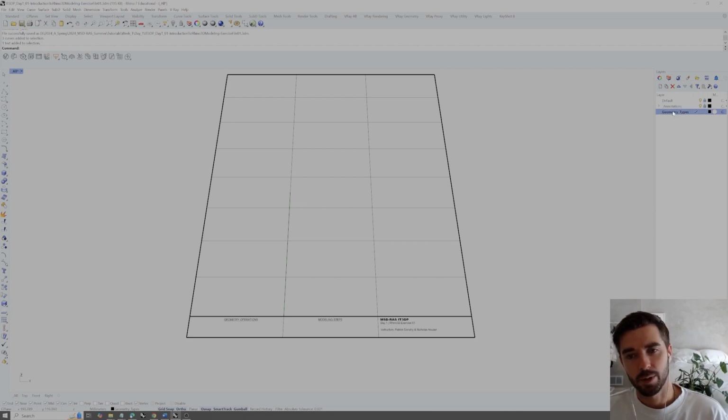So then the last layer that we have, which right now is empty, is geometry types. So these geometry types is just where we're going to be populating each of the steps of this video. What we could say here is just intro to modeling. So we can name that layer by clicking on it once to activate it, and then click again separately to enter into that text editing to rename, and then you can type whatever you'd like for that layer name.